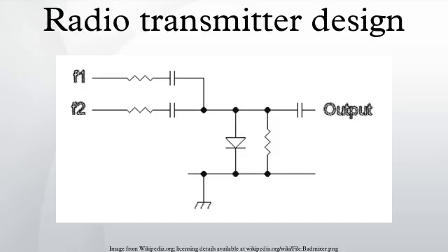Interference matters. Many devices depend on the transmission and reception of radio waves for their operation. The possibility for mutual interference is great. Many devices not intended to transmit signals may do so. For instance, a dielectric heater might contain a 2000 watt 27 MHz source within it. If the machine operates as intended, then none of this RF power will leak out. However, if due to poor design or maintenance it allows RF to leak out, it will become a transmitter or unintentional radiator.